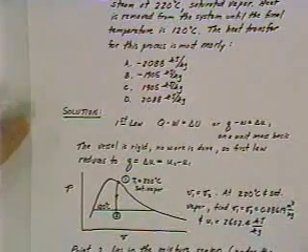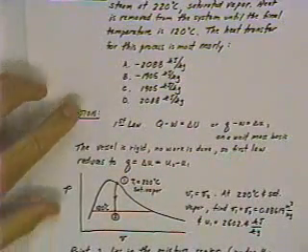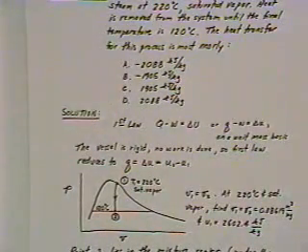If you're just looking at this problem, you can immediately eliminate answers C and D, the 1905 and the 2088, simply because both of these answers are positive. So you know your answer is either going to be A or B to start with, and you've eliminated 2 of the 4 answers right off the top because you know that the heat transfer has to be negative for this process.